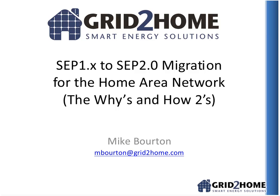The key difference in the residential sector is that you don't have a facilities manager sitting at every house who is knowledgeable on what to do and how soon to do it. So the answer was automation. We need to have the ability to get signals to a customer premises, whether through the AMI network or through the internet, to a decision-making device in the house. And then, based on policies that are set, that a customer is willing to accept a certain price for a certain device to work, certain things will come on and off based on that policy.